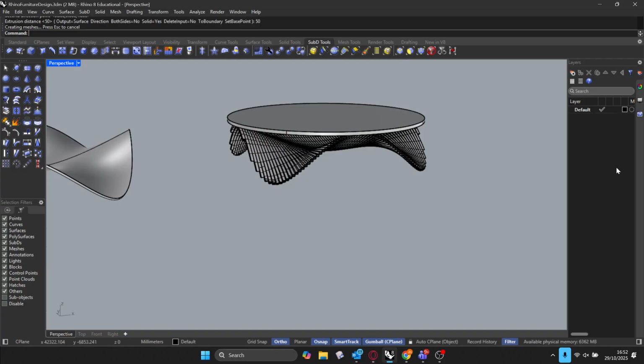It's less limited. So is there a sub D control point? Yeah, you can turn the control points on just by going here. Go to control points there. It's a different control point, yeah. Just make sure the control points are enabled, and now select a control point. Now pull it, and you move a control point.